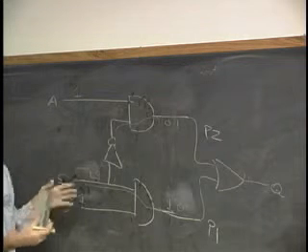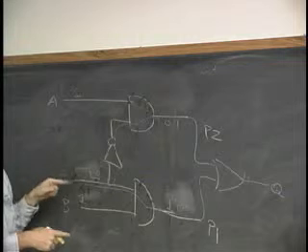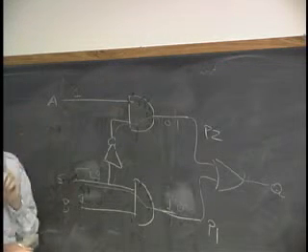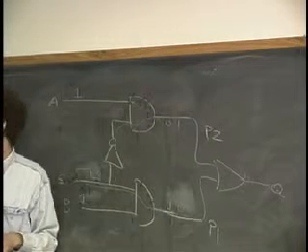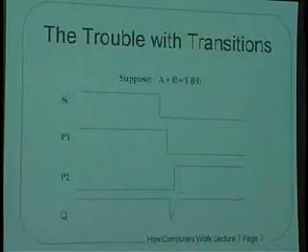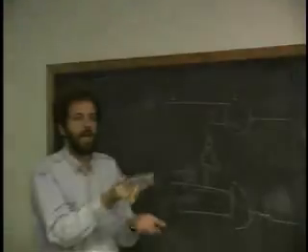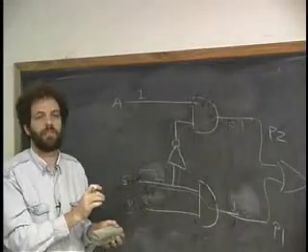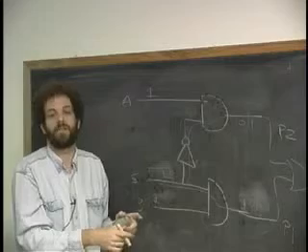And so a selector given 2 inputs, A and B, both of which are high, which is told first, choose B, and then next, choose A, may go through a transition where Q, which you see over there on the board, goes from high to low and then back to high again very, very quickly. As the internal circuitry of who's in charge of holding this output up goes through what's called a timing race. Okay? There's a race between turning this guy off and turning this one back on.